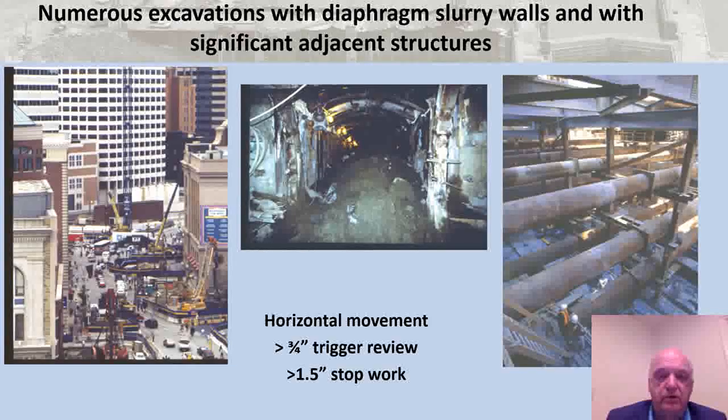Right up front, it was decided to simplify the performance monitoring so that we would limit any movement of these walls to 3/4 of an inch, at which point that was yellow and we'd trigger alerts. At 1.5 inches, we would stop work.